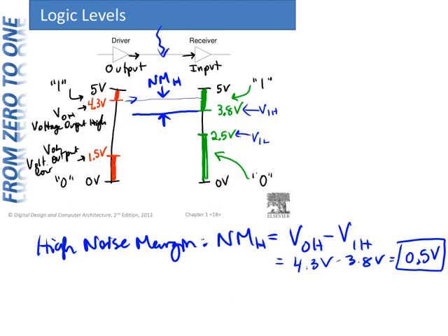For example, long wires. Similarly, we also have a noise margin on the low end. So here's our noise margin low. As we can see in this case, we have a 1 volt noise margin. The driver can send 1.5 volts. It can degrade by another volt, so get higher in this case. Degrading is making the zero an even worse zero.